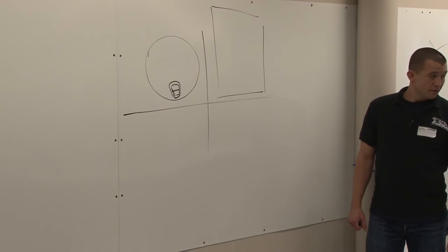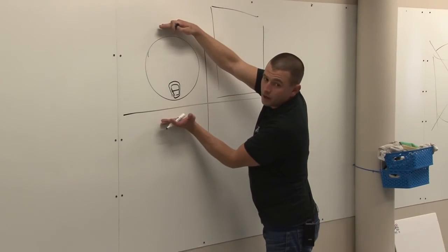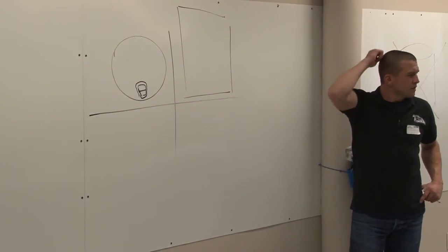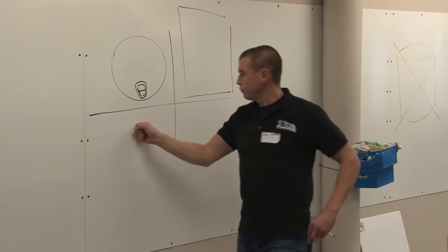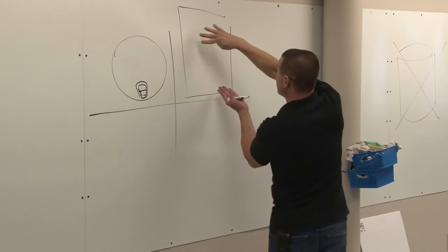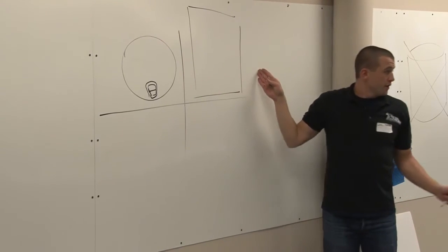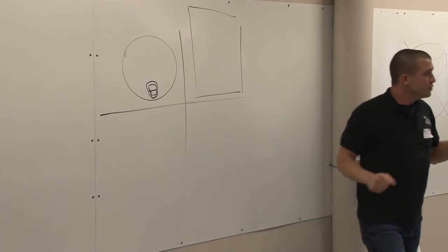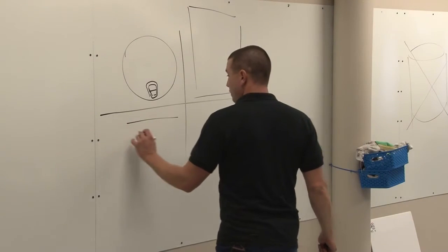Do they have alignment? Do the top of this picture and the bottom line up with the top and bottom there? No. What do I have to do to put these pictures in alignment? Josh? Rotate the side view 90 degrees. I could rotate this 90 degrees and go this way with it. You could. But do you usually see cans of soup laying on their side that way? So its most natural position, Josh, would be to move it below here.